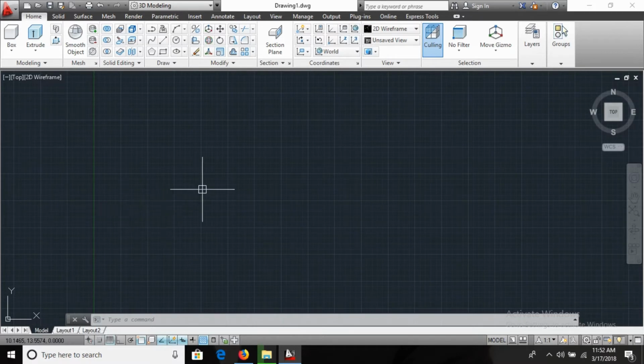If you want to turn off the coordinates, we click Control I, and then the coordinates will be off. That's the exact meaning of coordinates, and it shows the position of the crosshair that we need to remember. Next one is called info constraints.